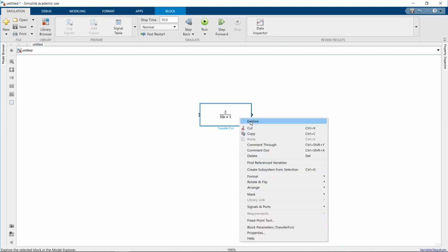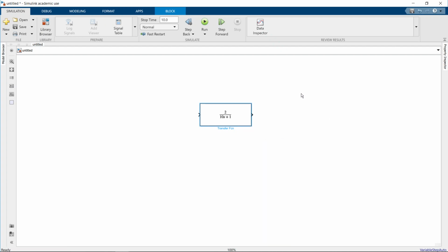But what I'm going to do is select this transfer function block, copy, or you can press Ctrl+C, and I'm going to paste it. Okay, so I'm just being lazy here, right? So I've got another transfer function. I'm going to change the name. This is GF of S. Doesn't matter, GF, that's your final control element. And then for this one, I'm going to change it to GP, your process.